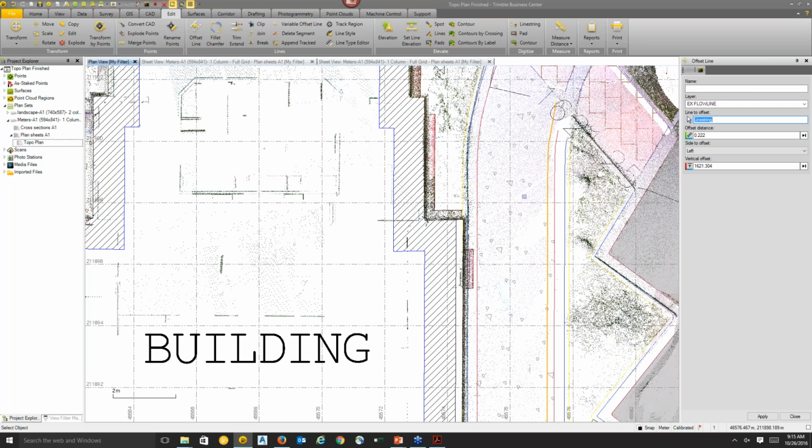Or what you can do in the case of a ground region, if you extract the ground from the point cloud and some of the ground region maybe takes part of a building or part of a tree stump, is take that ground region and extract again from it and run the classification command again just on that segmented region and see if you get better results there.